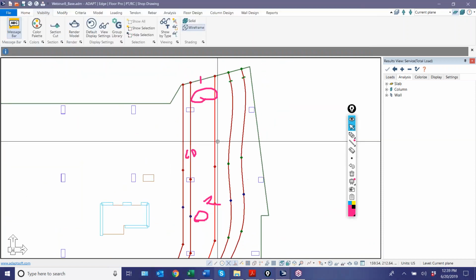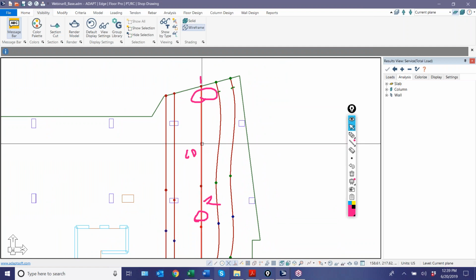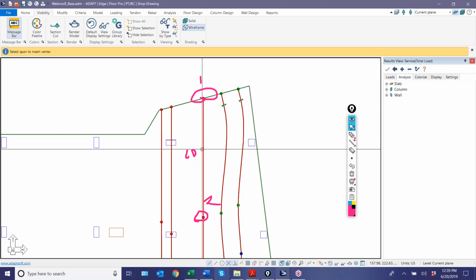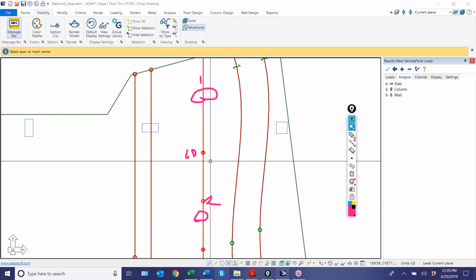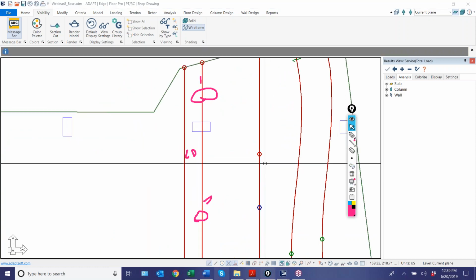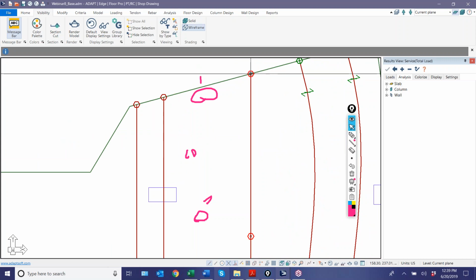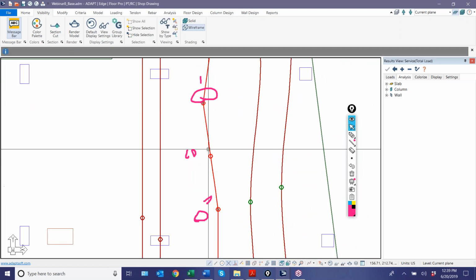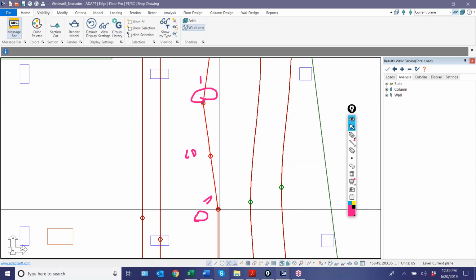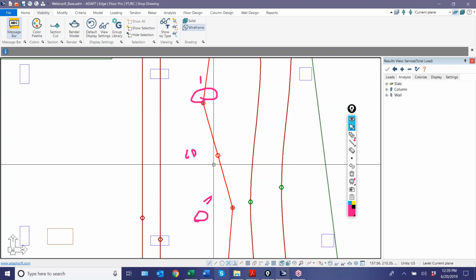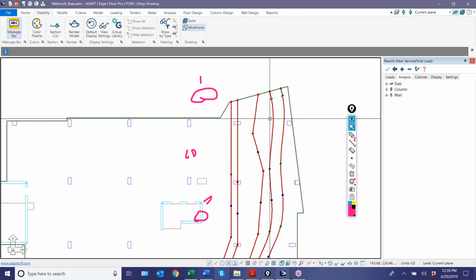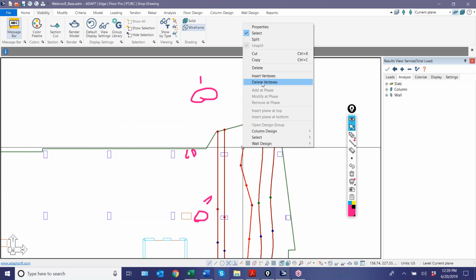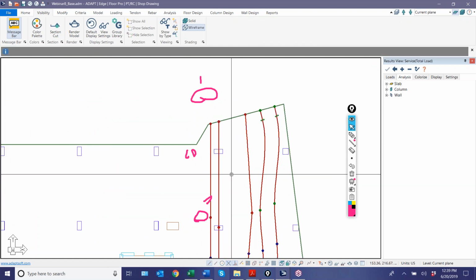Here we can right click. Let me go back and make sure that's selected. We're going to take this tendon, right click, and we're just going to insert a point, and that inserts a modifiable point for the cable. So you can see this here. I now have an anchor point. This is a control point here. I can move that. This is actually the cantilever down shape, and then I've added this span here where we have a control point at this location also, and this is a reverse parabolic shape. By default, it's reverse parabolic when we add the span, and you could add spans using that option. Right click, insert, or delete a vertex. Here I'll delete this one, and that goes back to the original shape.